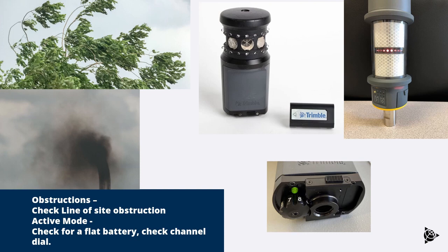If you're using active mode, check that the battery hasn't gone flat since you started work, and check that the channel dial is still set to the correct channel. This may have been bumped accidentally or may be set incorrectly.